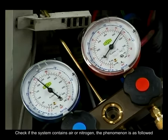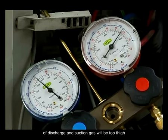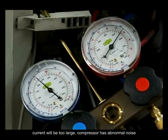Check if the system contains air or nitrogen. The phenomenon is as follows. When it is running, the pressure and temperature of the discharge and suction gas will be too high. Current will be too large. The compressor has abnormal noise, and the pointer of the pressure gauge will shake.